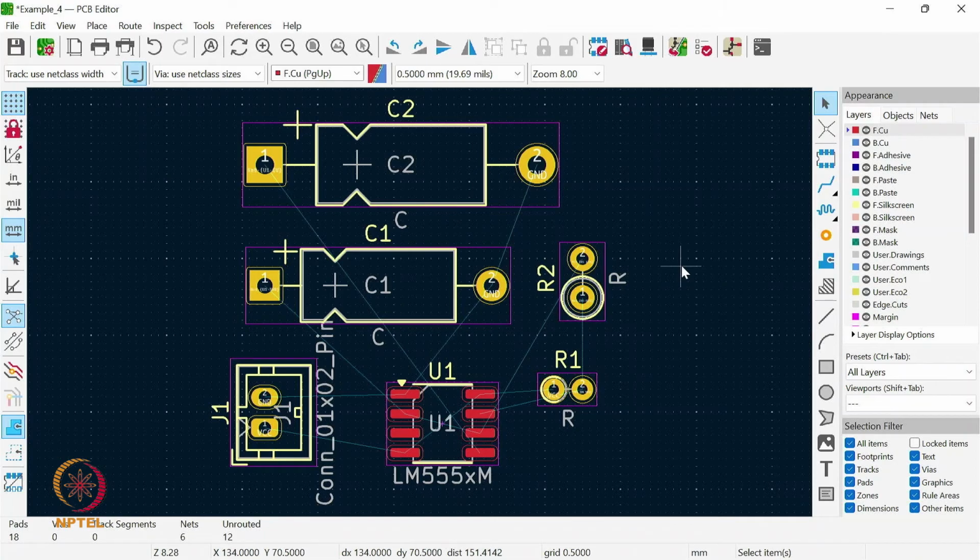With practice you can do it fast and in a more efficient way. If you have more than 10, 15 or 20 components, then it comes with practice: how do we place them each apart from each other and have all these rat nests available. So now we have this PCB to route, where we see all these rat nests, which say that all these connections need to be made, which are shown by these light blue color lines.